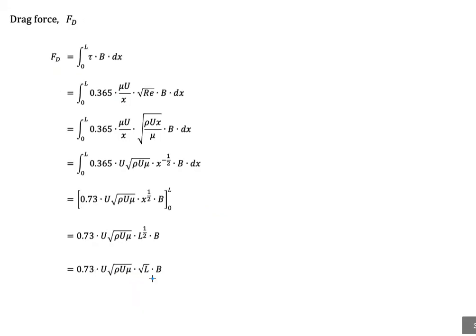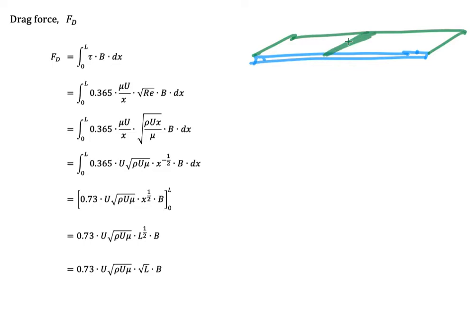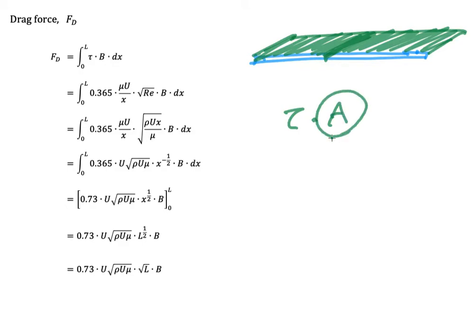And then we could calculate the drag force. So the drag force, the idea is simple. We have a plate, so we have a shear stress on this small local area, and then we need to calculate the total shear force here by using the idea of shear stress times A. So the area here can be written as B, the width of this one from here to here, and the total length of x.